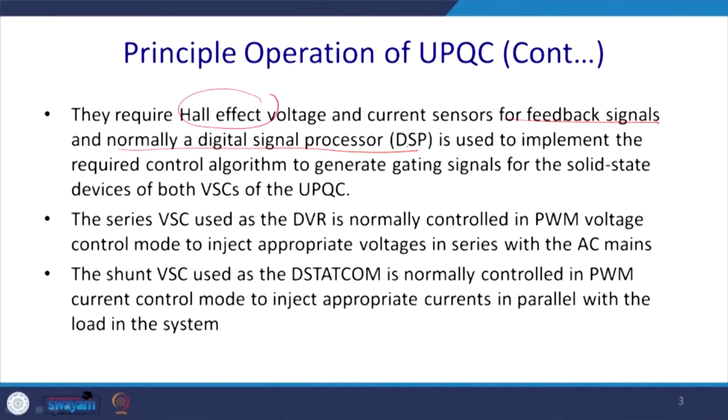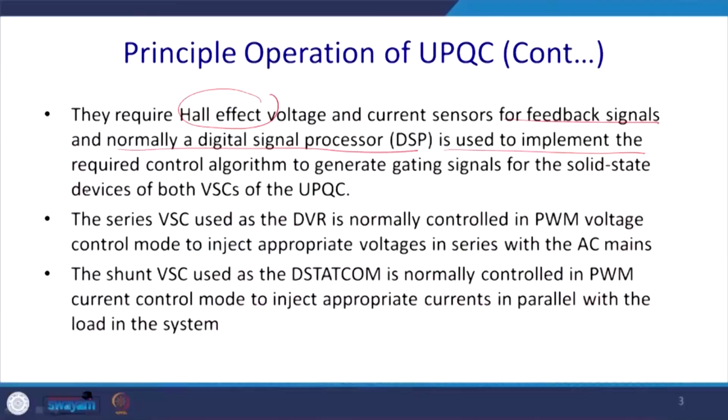Normally a digital signal processor, DSP, or maybe an FPGA, is used to implement the required control algorithm that we have discussed already, the different kinds of control algorithms, mainly Akagi's method, the instantaneous reactive power theory, or the SRF theory. It is used to generate the gating signals for the solid state devices of both voltage source converters of this UPQC.